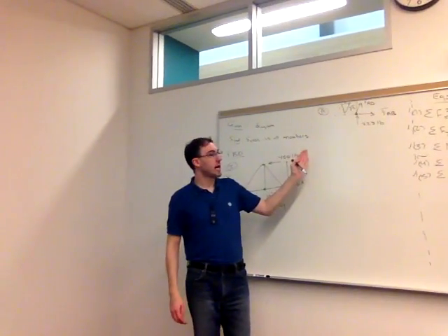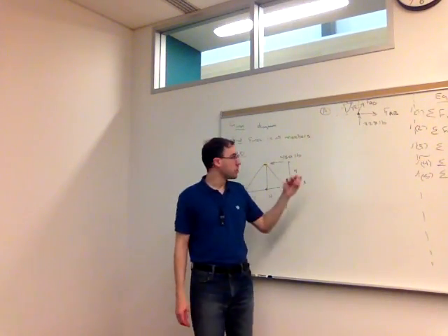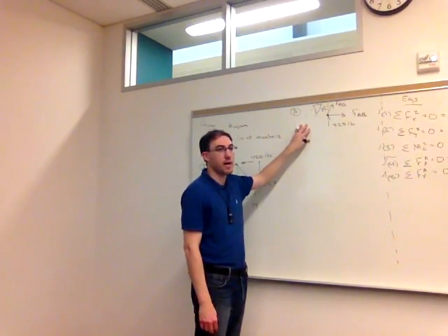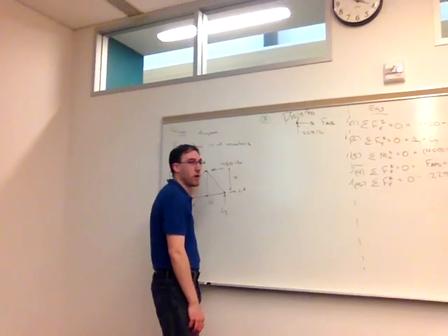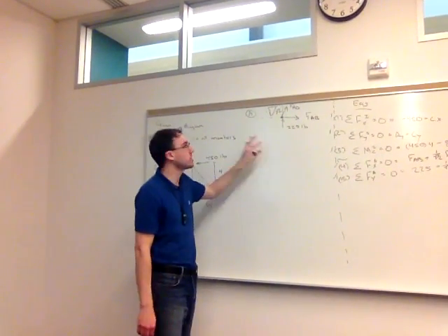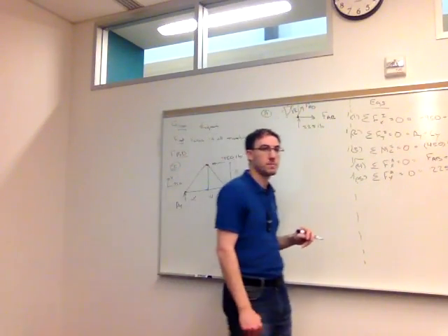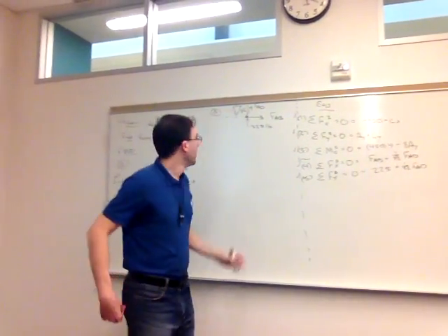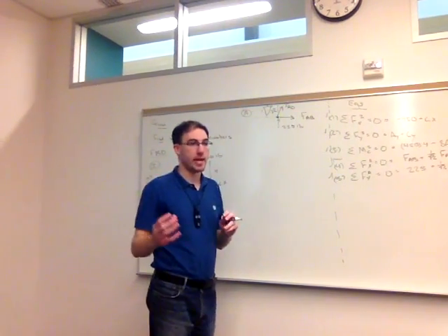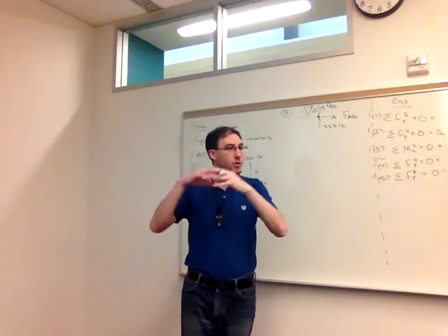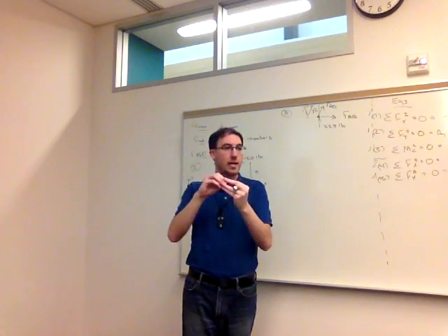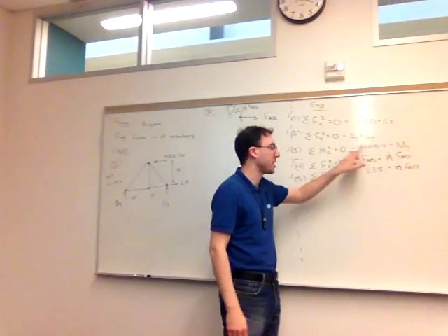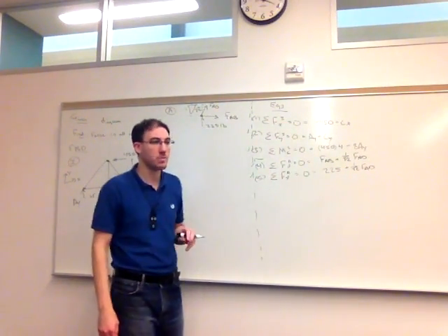So using free body diagram A, we've solved for two of our unknowns, but there are still three left. We've used everything out of free body diagram A and free body diagram 1 at this point. So the only way to get more equations is to draw more free body diagrams. Now we can move on to another pin and do the same thing. At this point, it's usually easiest to go to the next pin over, or a pin that's attached to the one we just solved for, because we'll be able to start using some of the answers we already have in the next pin.